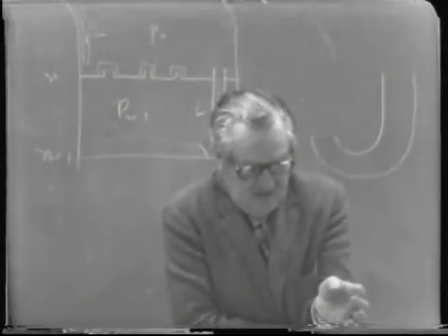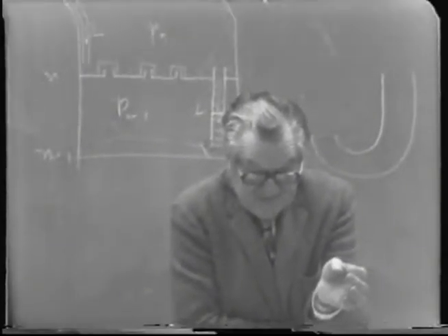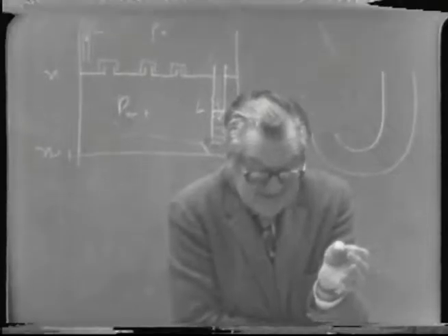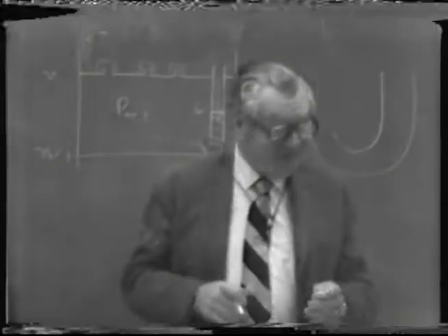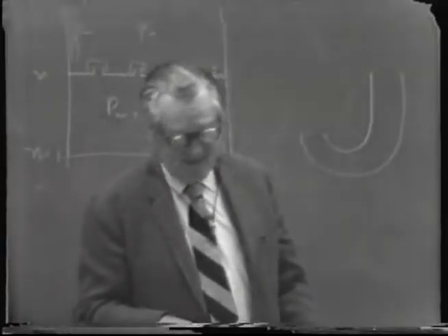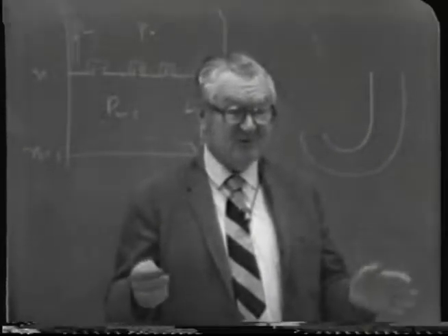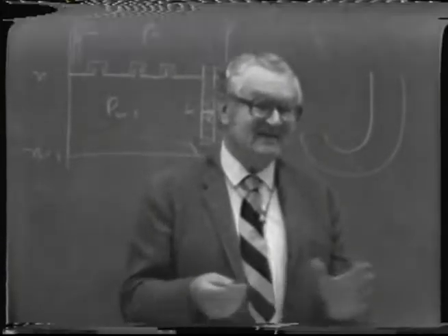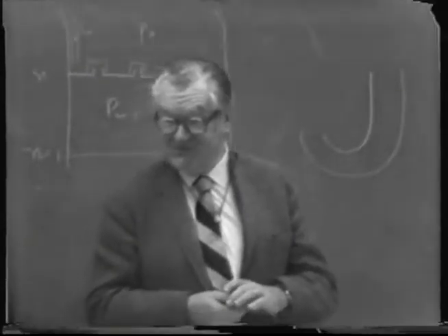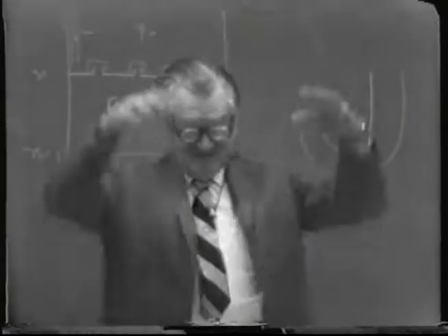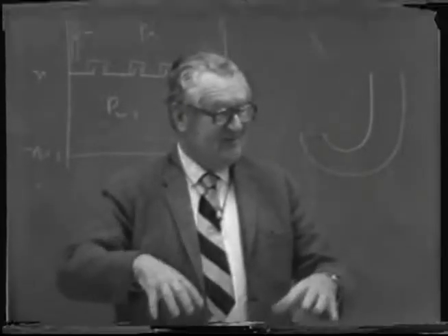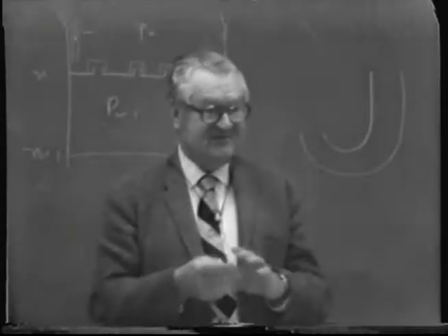Well, what happened was that they let liquid get through all right, but it all went down through the holes, and nothing was going down through the downcomers. And that constitutes what you call a shower tray. If they're properly designed, then you can get a bit of efficiency by a shower type tray where the liquid is cascading down in bubbles and the vapor passing up through, but it's a very poor design.